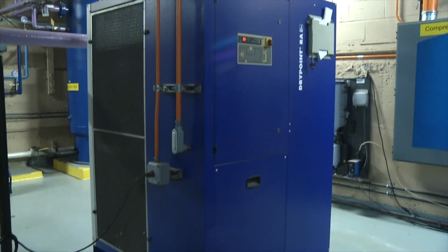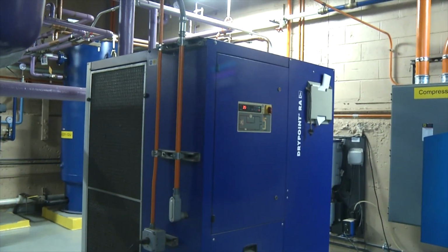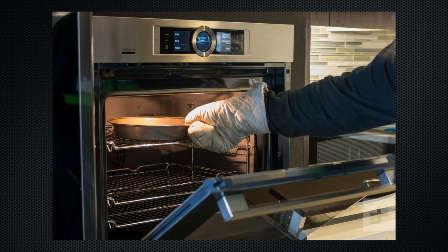The second biggest piece of equipment in the compressor room will be the air dryer or air cooler. They're the same thing. People don't realize that when you pressurize air, it gets hot. If we go up to 100 pounds per square inch of pressure, the temperature of the air before you cool it will get up to 530 degrees Fahrenheit. Take a look at your oven. It doesn't get any hotter than that with your highest oven setting. So it's very, very hot, and that can cause problems in and of itself.